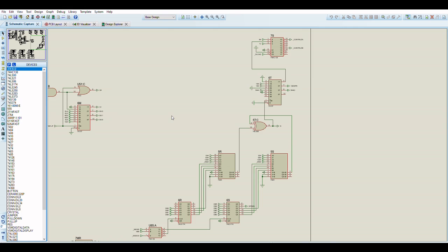This is also why adding the extra tall complete vertical strips sprites logic was really quite a simple thing to do, because just turning off that vertical comparator meant that it just kept on rendering sprite data, and all of the rest of the logic internally was all aligned already with having your 4-bit 0 to 15 value inside the sprite cycling round perfectly well, because it was subtly dealing with all of this extra logic anyway, or extra desire to render 32 vertical pixel sprites anyway.